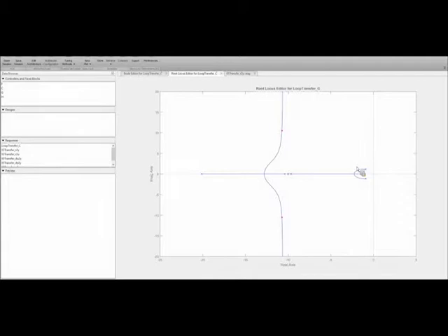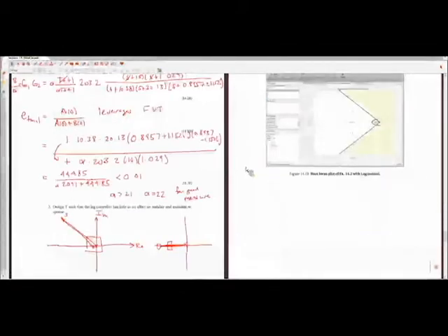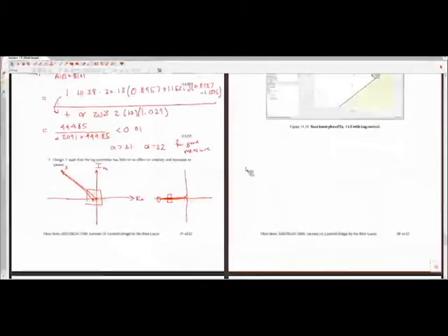So just to note, dominant dynamics here, these aren't really that important. So we're going to be putting our lag controller dynamics all within this region. So we're going to select our 0 for our lag controller to be around 1. That's what we're going to start with. So just kind of typing that out in text.